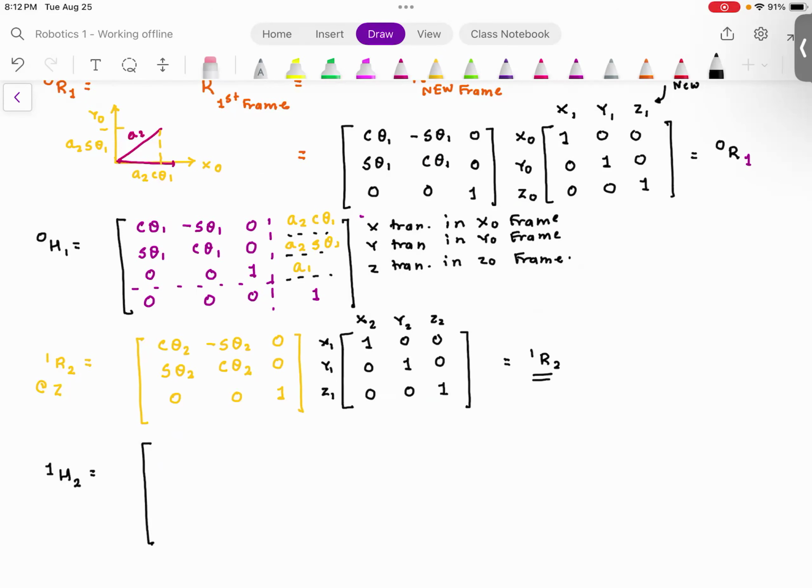Please note, in homogeneous transformation, you have to use this matrix, not this matrix. In this case, this matrix is equal to this matrix because the projection matrix is identity. But I promise you that this projection matrix can have negative terms. One could be flipped, and in that case, you have to carry out the multiplication explicitly. So this matrix needs to go here, not this matrix. Everyone understood this? Very important.